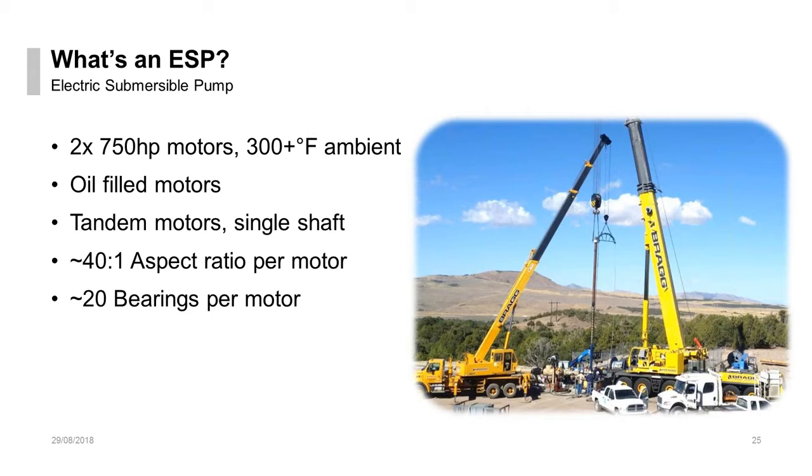And this is especially relevant because most of your inverter duty motors are designed with a couple of very important tweaks. Usually one of the bearings is either non-conductive or insulated, and that helps reduce the likelihood of having circulating currents inside the motor.